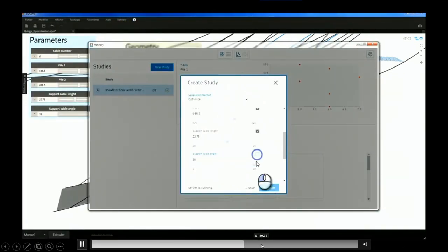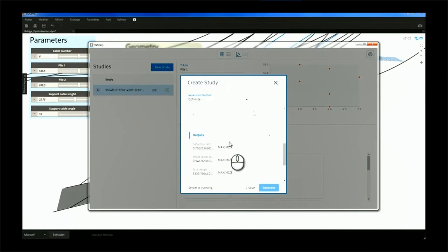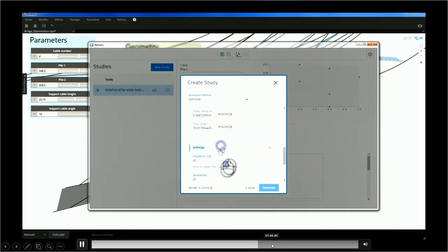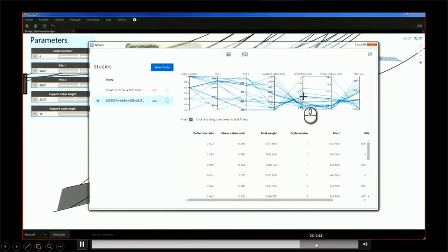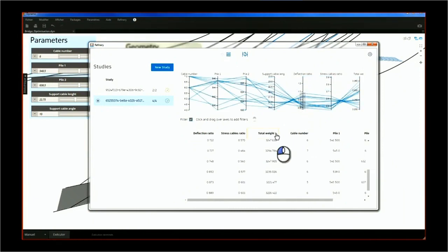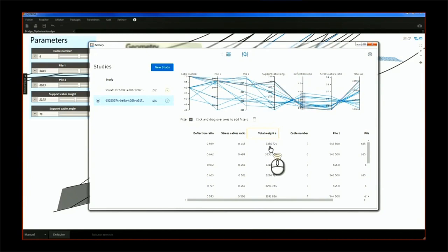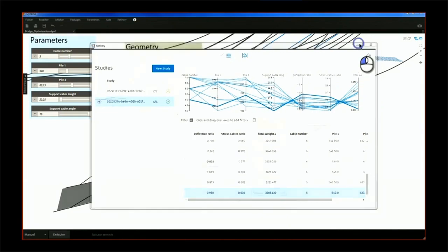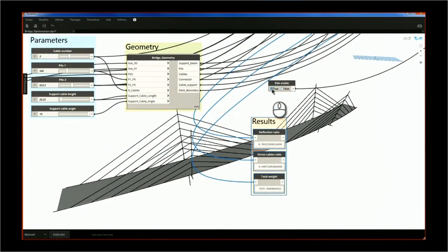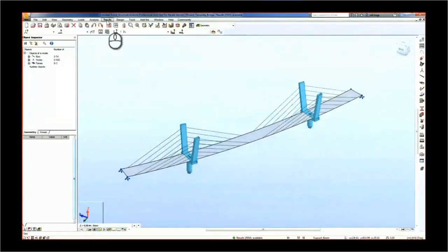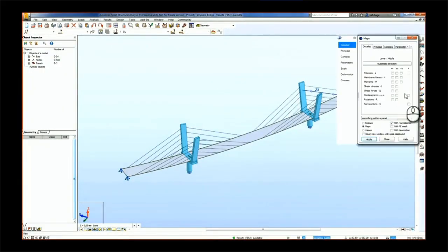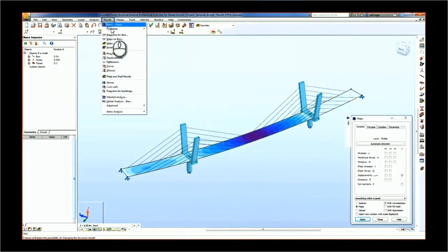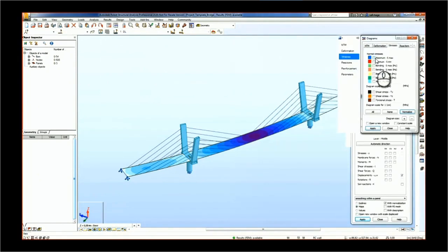Then what he did, after selecting a certain one, he sent it to Project Refinery, and he asked the generative design algorithm of Autodesk to optimize or send a few iterations of the design. So this is what Project Refinery came up with. Same story, checking the total weight, the stress, the deflection, picking a certain item that satisfies the requirements, and then that model will be pushed for final design. It still needs some refinement. You're not going to do everything in generative design. As I mentioned, it's just an optioneering tool, just generating multiple options. So these are the major two ways that are currently done in generative design.